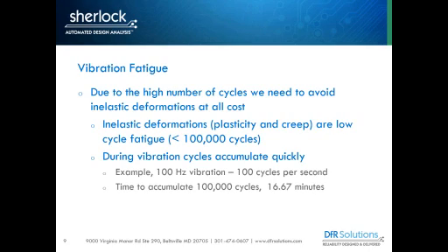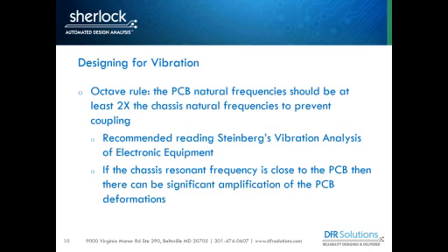So that's usually why, if you are doing a vibration analysis and you see any type of plasticity or inelasticity, that's a showstopper. That product cannot be used in that environment because it's not sufficiently constrained and it's going to fail very quickly. So when you do a vibration analysis, it almost gets down to pass-fail, because if I get any plasticity occurring, things fail almost instantaneously. Once I prevent that, I go to elastic, and now we're talking tens of millions of cycles to failure. So there's a really abrupt transition between pass and fail during vibration.